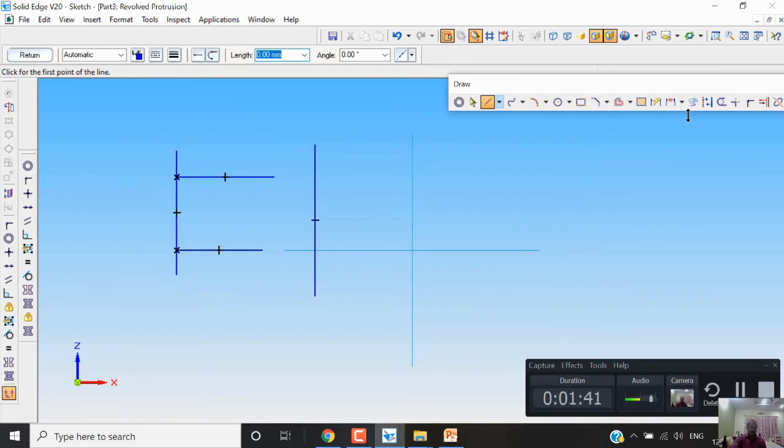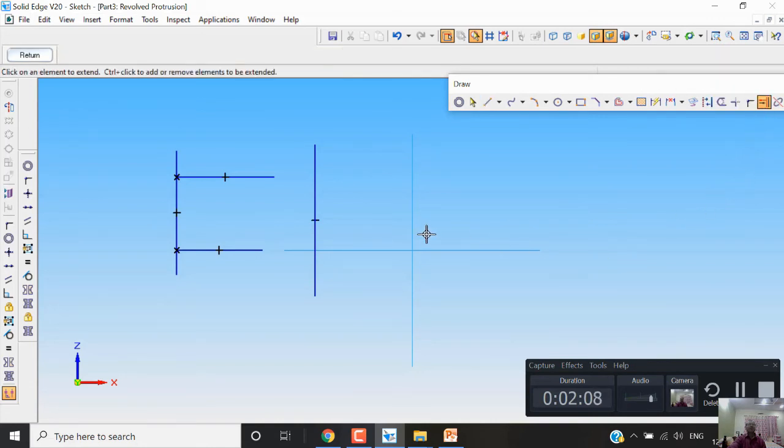So extend command means in Solid Edge, whenever we draw profiles in some areas of drawing, we need to extend the line in order to close the profile. In such cases, we need to extend from the draw toolbar. So let us see how this command will work. From the draw toolbar, click on the extend to next.